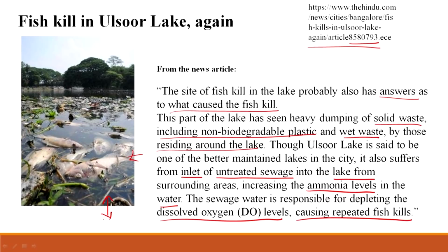So, what is happening here now that you are relatively more knowledgeable? You will know that again as we go through the relevant material and understand the system. First, when we say untreated sewage coming in, or some wet waste like kitchen waste, these are relatively reduced forms, and they can be oxidized or mineralized. But what do they need? Obviously, they need an electron acceptor, which is oxygen. And obviously, your waste or your feces is competing with the oxygen in the water.